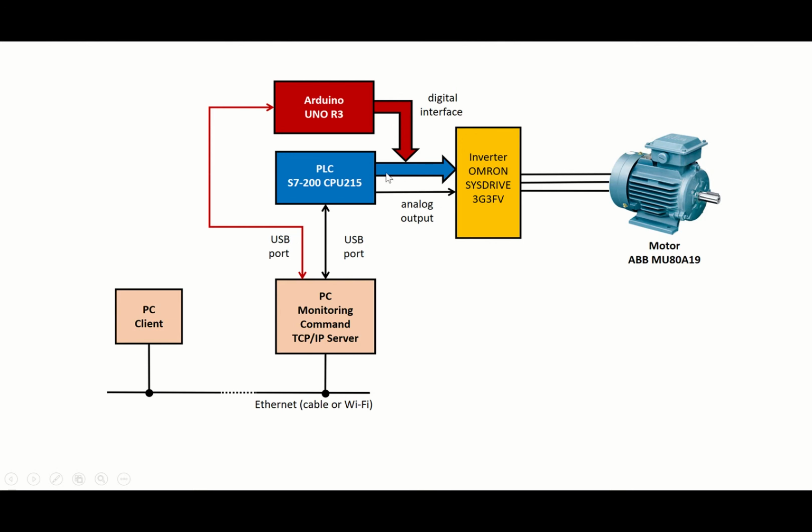So you can access velocities, command velocities with a digital code, but also jog the motor with an analog signal that is regulated to be proportional to the frequency of the motor. So you can have 0 to 15 hertz, 0 to 50 hertz with a signal from 0 to 10 volts. So analog and digital interface.